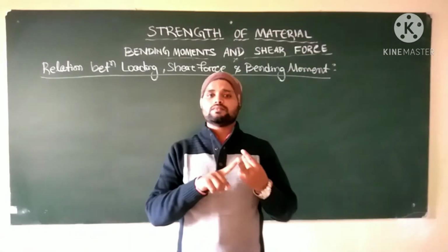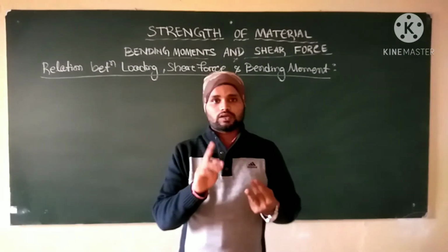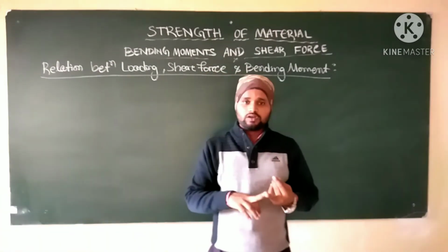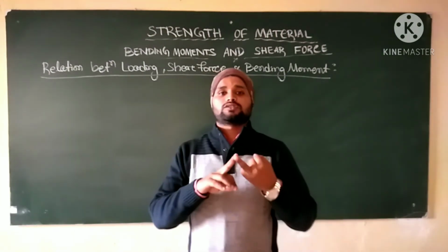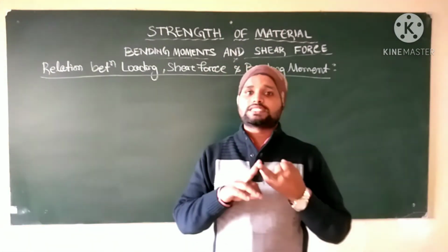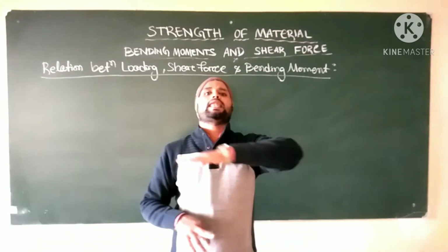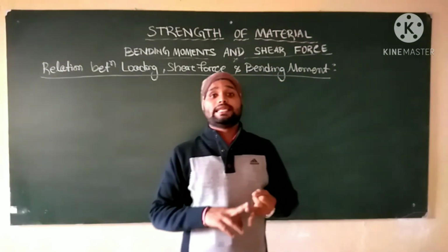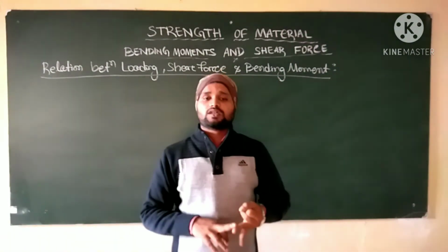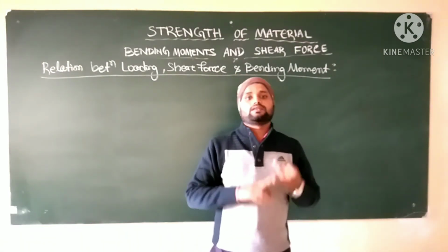Second point, if there is no load between 2 points, then the shear force does not change. That is, the shear force line is a horizontal line, but the bending moment changes linearly. That is, the bending moment line is an inclined straight line.